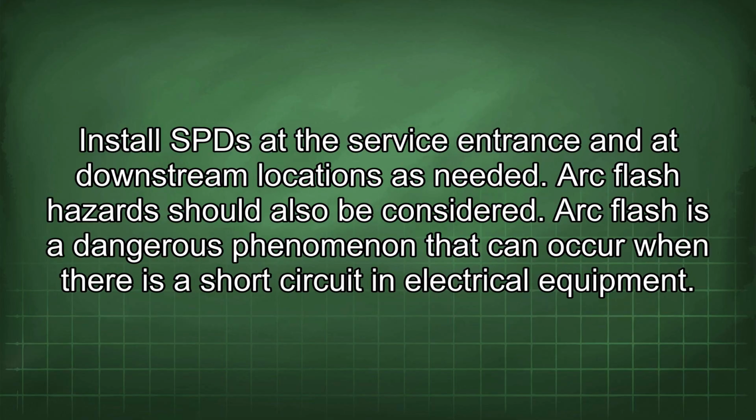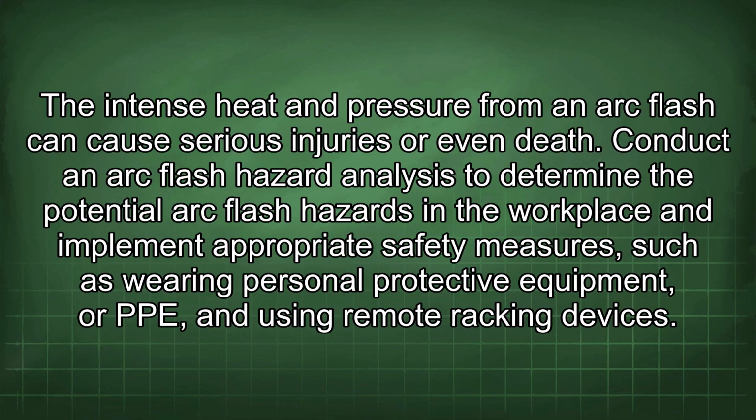Install SPD at the service entrance and at downstream locations as needed. Arc flash hazard should also be considered. Arc flash is a dangerous phenomenon that can occur when there is a short circuit in electrical equipment. The intense heat and pressure from an arc flash can cause serious injuries or even death.